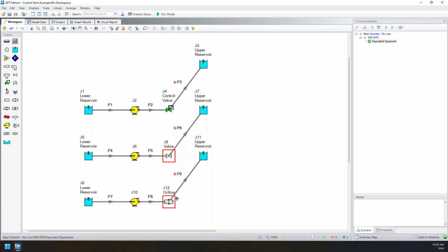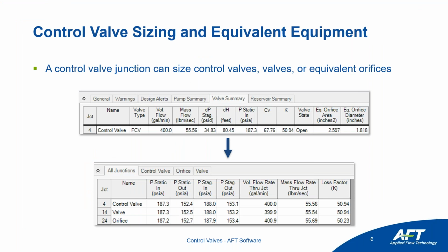These are just fixed elements. You can think of it as that fixed system curve. And when we start changing the pump curve, obviously the flow rate through those components is going to change. So while it's going to be consistent for this one case, once you make changes to your boundary conditions or to your resistances or to your pumps and other components, these systems are going to deviate from one another. So just one caveat to consider.